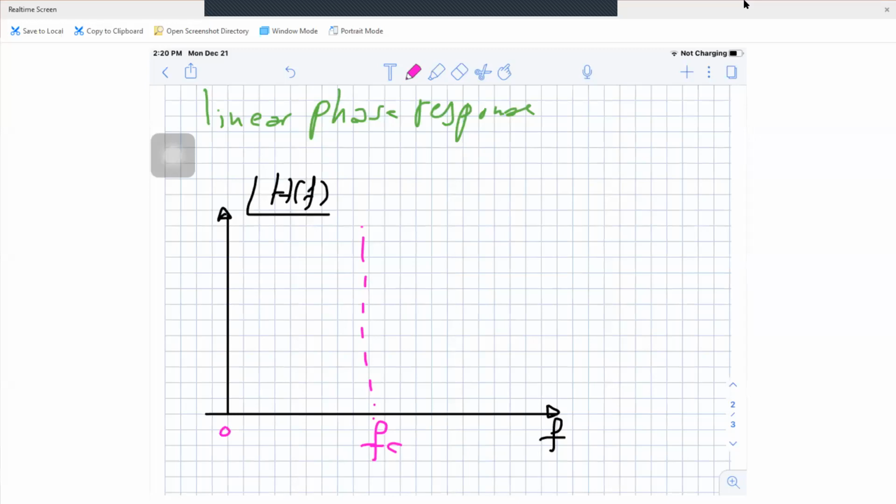I'm going to pick up the signal which lies inside the passband region. Of course, outside the passband region, I'm not going to take care about the phase of the filter after the cutoff frequency. So, for example, look at this example. Here we have linear phase. This is a linear phase, okay? But outside the passband region, we may have nonlinear phase, so it's okay. We don't have any problem. Look, the equation of the phase here must be a straight line equation.